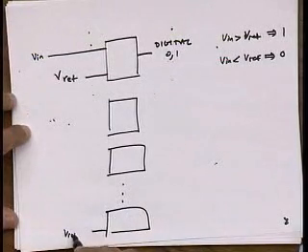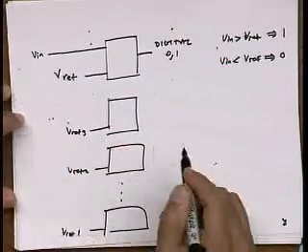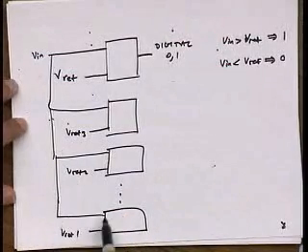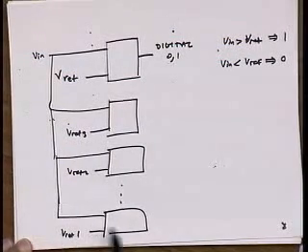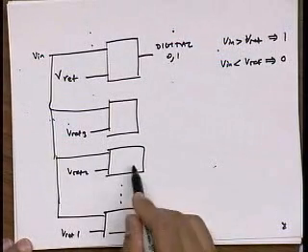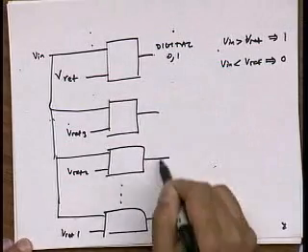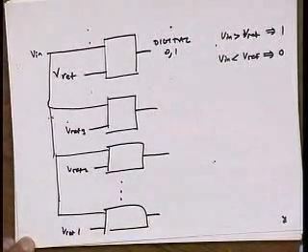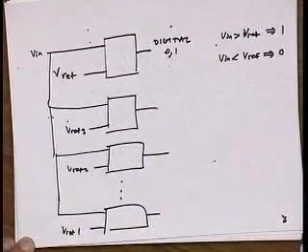So this is, let's say, Vref1, this is Vref2, this is Vref3, and my input signal is going to drive all of these. And let's say this is the smallest reference. So if it's bigger than this, I know it's at least this big. And then as I go on, at some point, I'm going to see a shift from lots of 1s to lots of 0s. The top 1 tells me how big my input is, right? Brute force, but it works, and it's very fast because it's as fast as I can make this comparator, right?